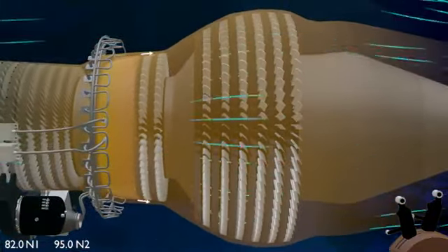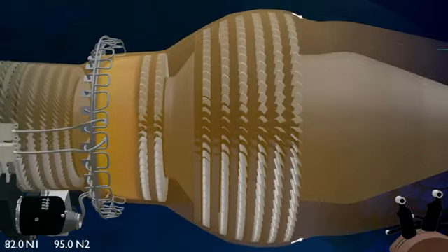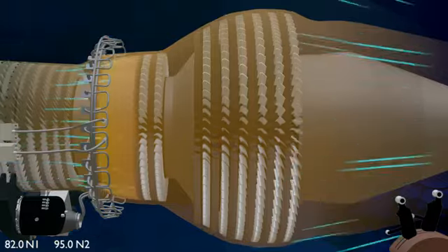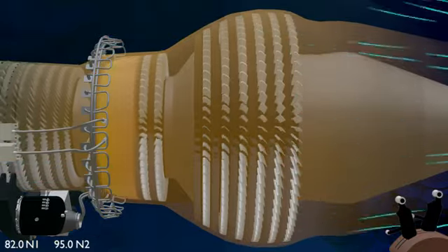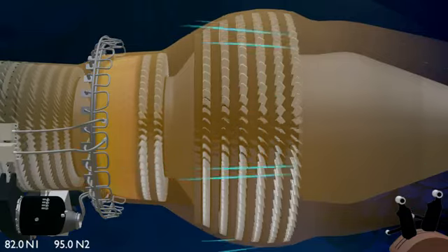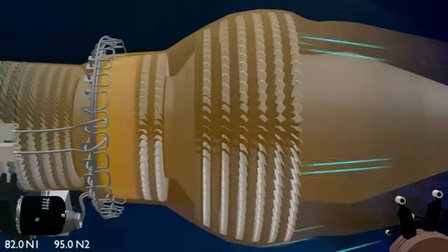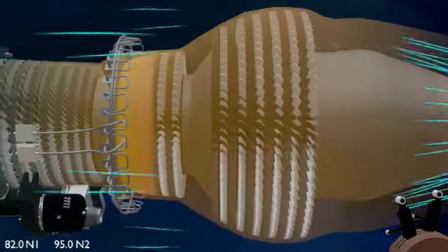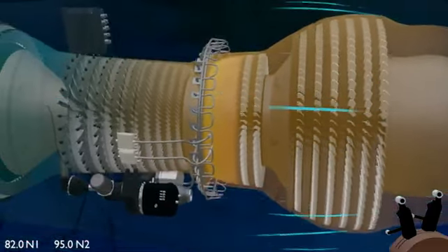A significant amount of combustion gas forces now vacate the turbine section without hitting the rotor blades. This results in loss of energy, and the engine has to burn more fuel to reach the desired power. To comparatively burn less fuel and get maximum efficiency, the clearance needs to be as small as possible, so that the majority of the gas forces transfer their energy onto the turbine blades. Let's look at the two systems that help the engine achieve minimum tip clearance.